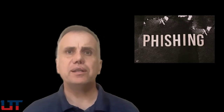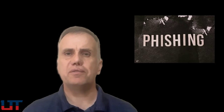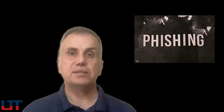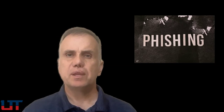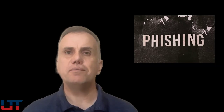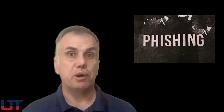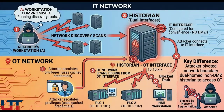In this scenario, an attacker sends a phishing email to an office employee. The email contains a malicious link. The employee clicks it and their workstation is compromised. The attacker now has control of a machine on the enterprise IT network, level 4 in the Purdue model. From that workstation, the attacker runs network discovery tools.